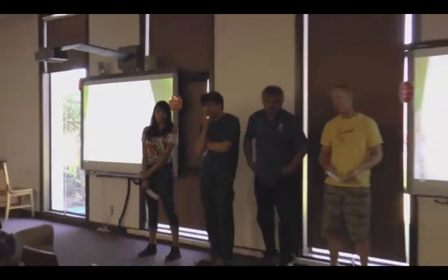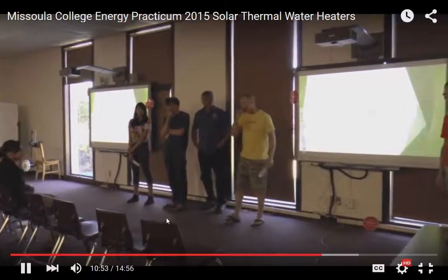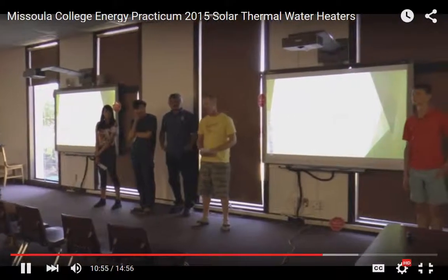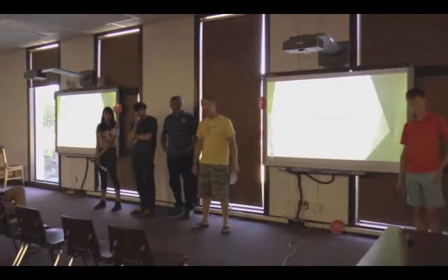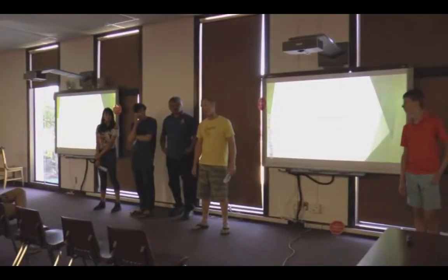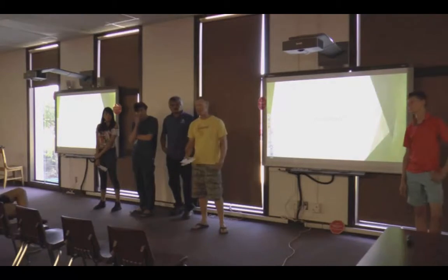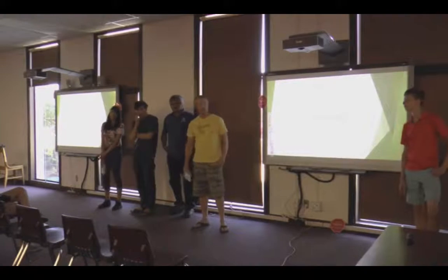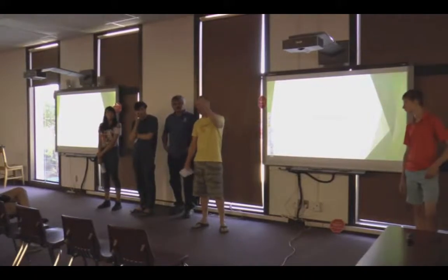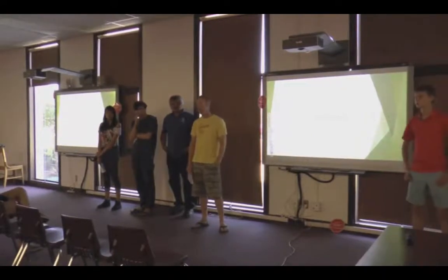You've mentioned solar insolation several times. What does that mean? So the insolation is the amount of solar radiation hitting the earth at any given point. It's usually measured in watts per square meter. An average of 1,000 watts per square meter is used for calculations. But a little bit of clouds will drop it down from 1,000 to 250. That's a significant drop.